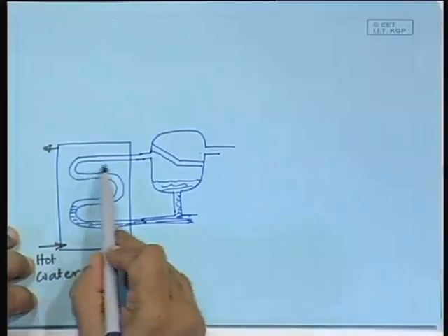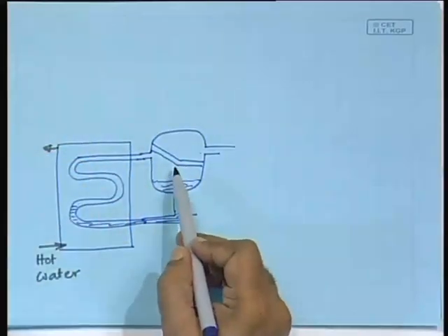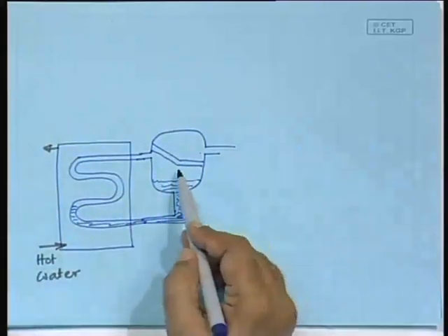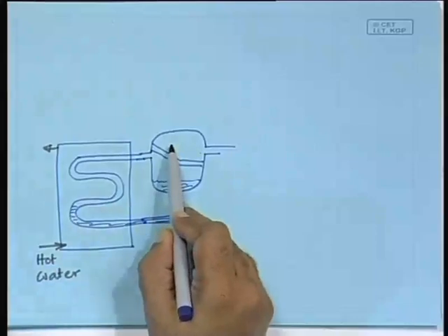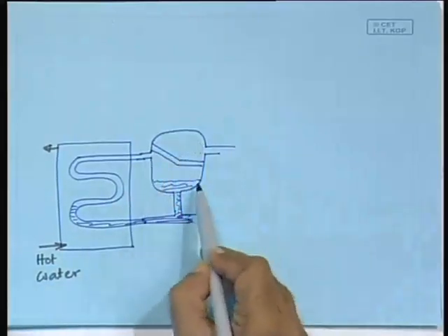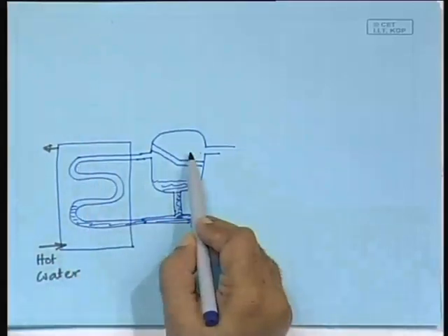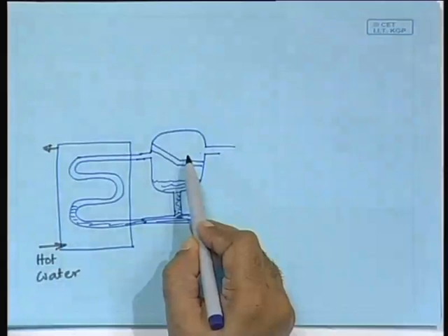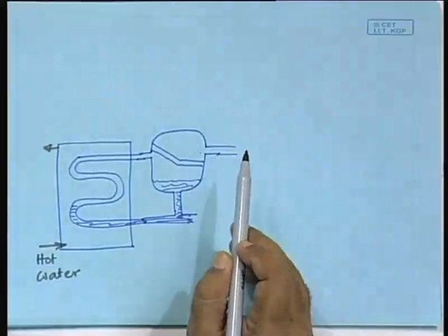Okay. So, as it goes to the separator, essentially it goes through a baffle, so that the liquid part is collected and drops down, and the vapor part goes through. The pressure here is slightly reduced in comparison to the pressure here, as a result of which those tiny droplets also evaporate to produce superheated steam. Okay. So, not steam, ammonia.